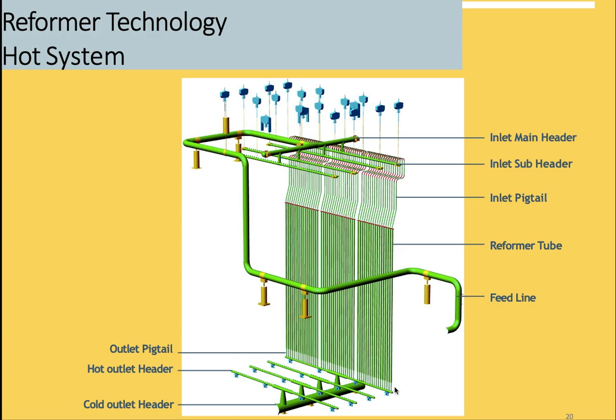Tube rupture we can discuss now. What are the symptoms of tube rupture? Sudden pressure drop. Okay, furnace flame instability, high O2 or CO in the furnace, and emergency shutdown immediately.